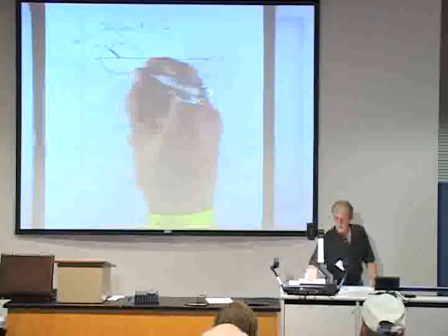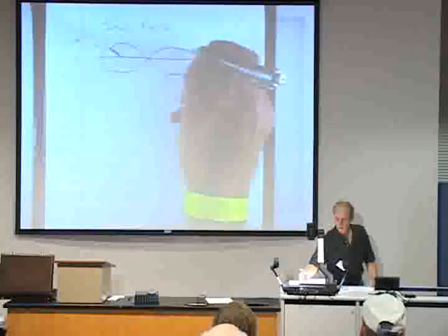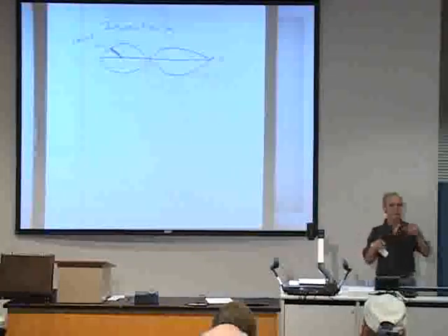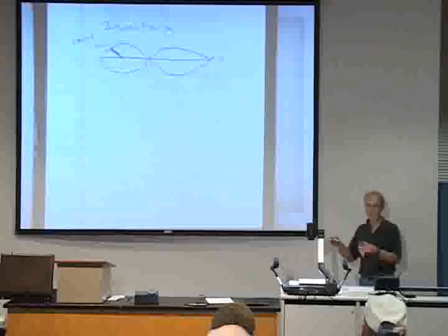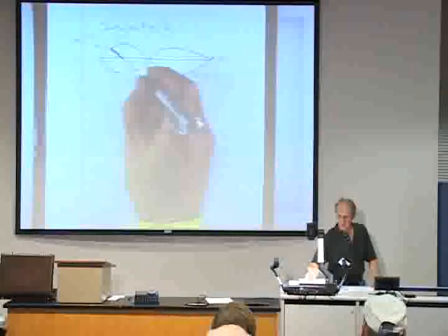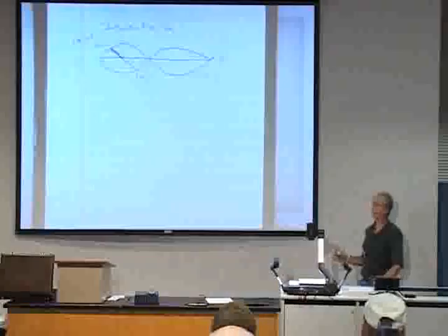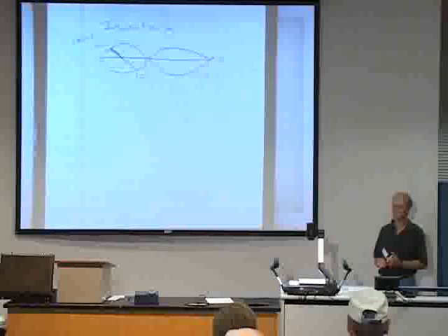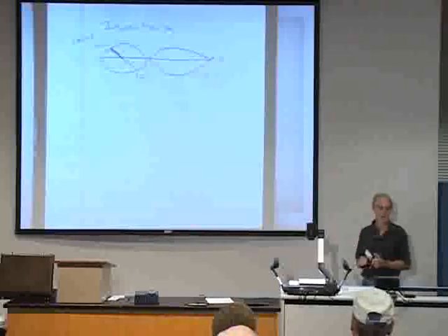240 is actually two single phases that are inversed from each other. That's a 240 sine wave. It goes in both directions, meets at 0, and goes the other way. And so the difference from that 120 to that 120 is 240 volts. And that's what you'll often hear about, single phase 120, single phase 240. Okay, the inverter will do that.